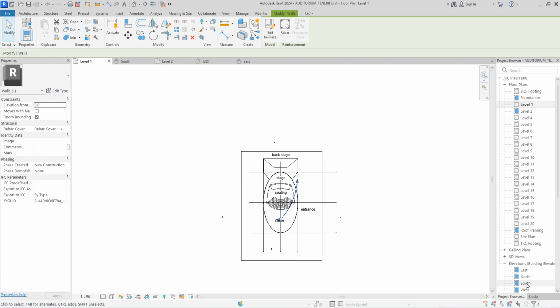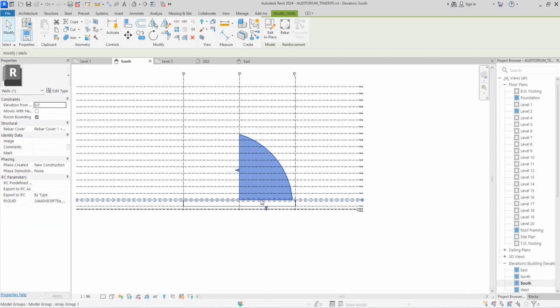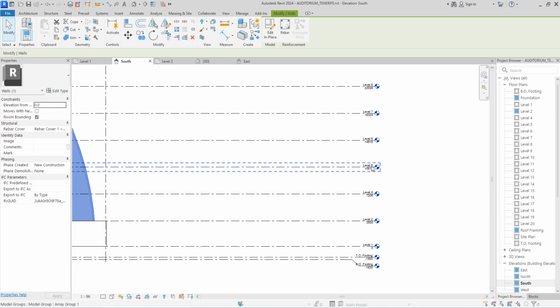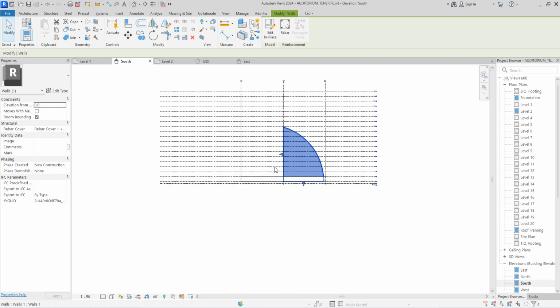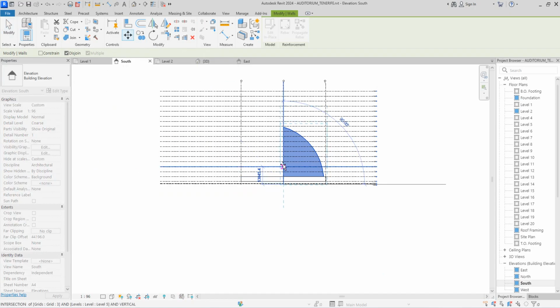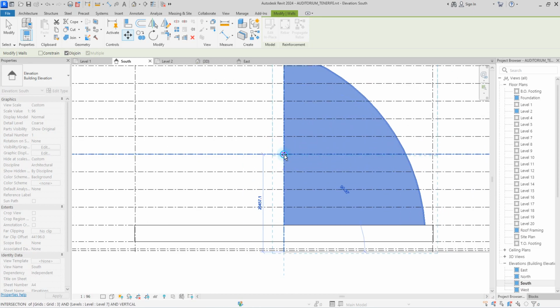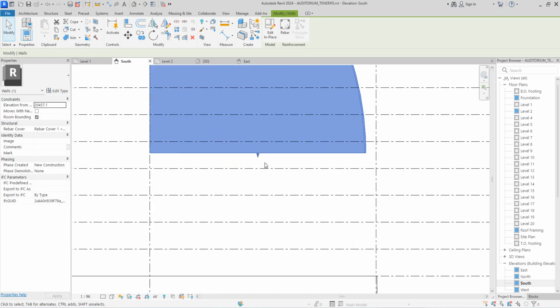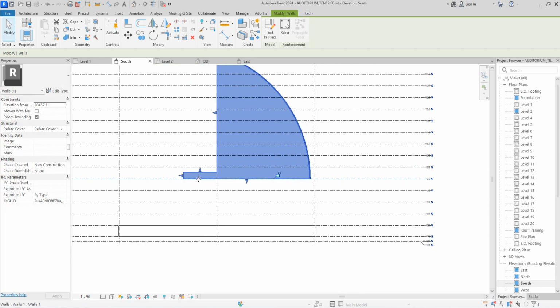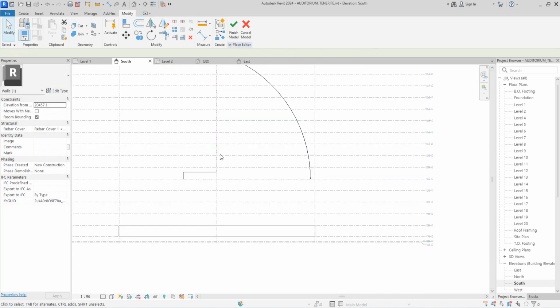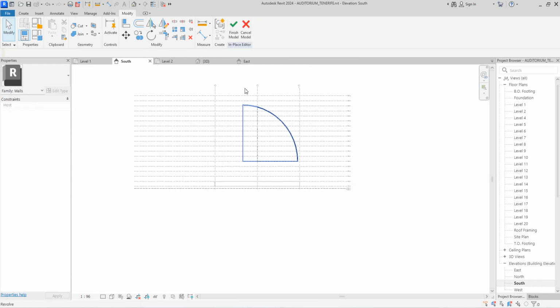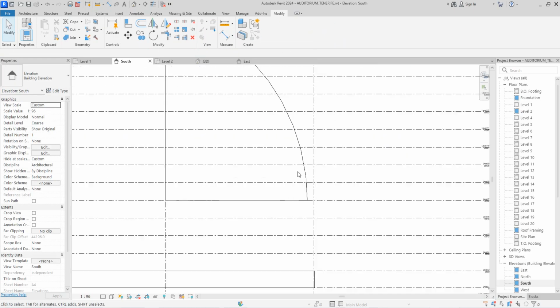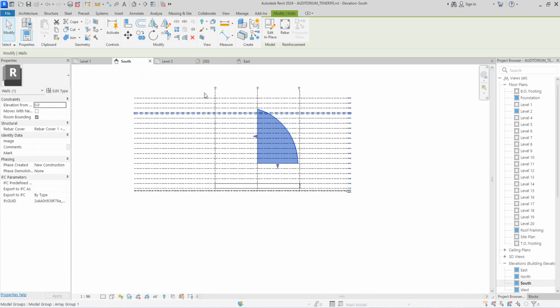So what we do here is that we go to start elevation, and this is where we are going to move it to level 5. Let's take it to level 5. So here we say move, then you take it to level, yes. So this is where the whole thing stays and lies. So you click there and say edit. So edit here, you drag this down. So we're done with this. Now you say finish. What we just need to do here now is to mirror this. And we say mirror.